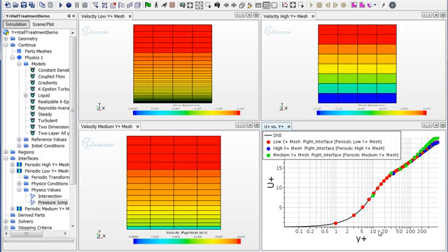The blue dots depict the solution on the high Y plus mesh. The cell next to the wall has a Y plus value of 34. This solution captures only the logarithmic region of the turbulent boundary layer. The viscous sublayer and the buffer layer are modeled by the wall treatment. We can see that both solutions, from the simulation on the low Y plus mesh and from the simulation on the high Y plus mesh, give similar results in the logarithmic region.